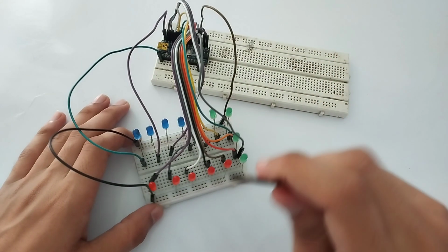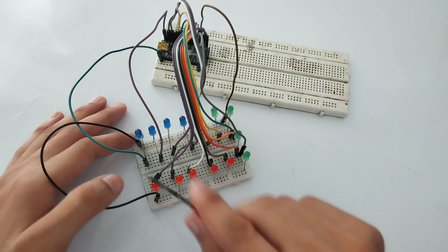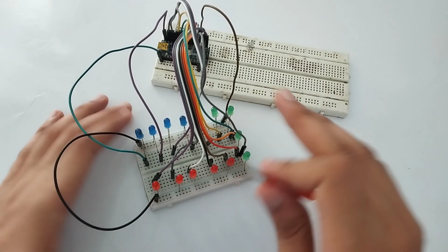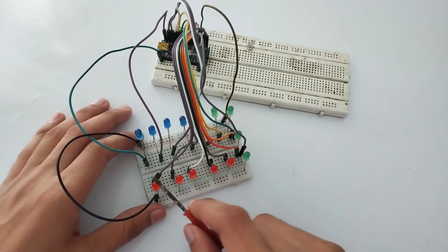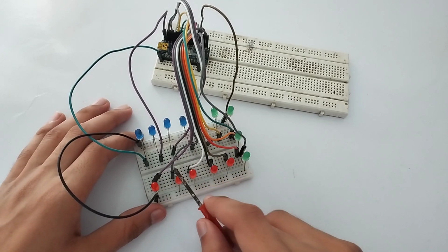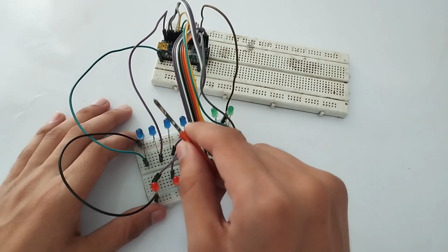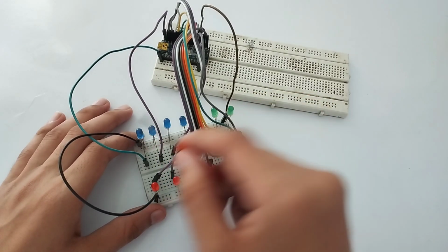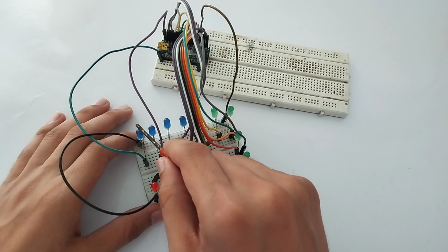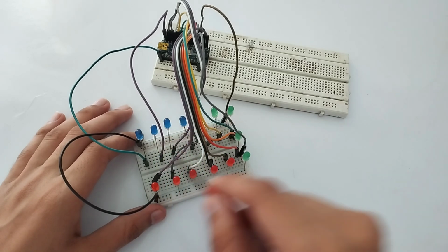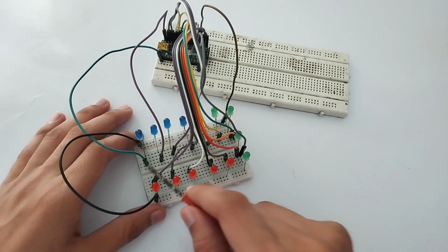One thing you need to keep in mind while making the circuit is the order of the connections. If you want to get a proper pattern among the LEDs, you need to connect this first LED to pin number D0, this to pin number D1, this to D2, and likewise this last LED would be connected to pin number D13. Or if you start from this LED, this should be connected to D0, D1, D2, and likewise this should be connected to pin number D13, right?